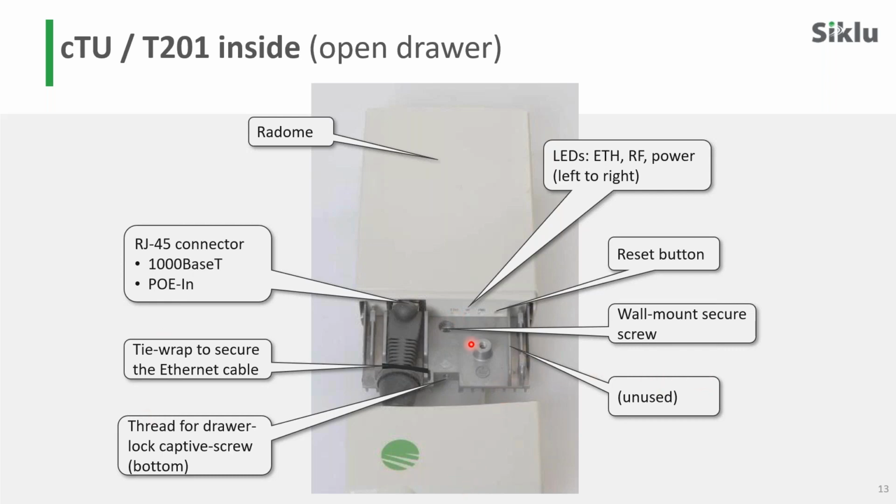And here there is an optional ground point that was a provision, sorry, for the case where we would not get safety clearance to not use the grounding point here. As it stands, we have all our safety clearances without grounding the unit independently of what is already provided by the electrical ground on the data cable.